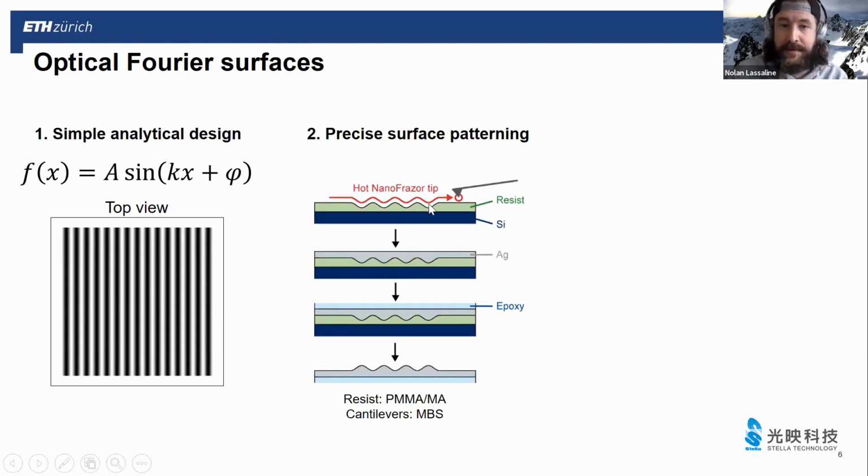And so we pattern the surface with the 3D profile that we care about. The way we go about transferring it to optical materials, in this case silver, which is what I'll be talking about today primarily, is we use a thermal evaporator. We evaporate the silver such that it fills up the profile. Then we take glue, stick it on the back of the silver, and simply pull it out of this so-called template. This is called template stripping, a common process in a lot of optical devices.